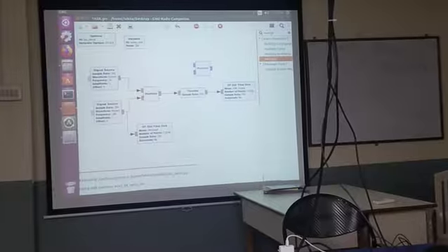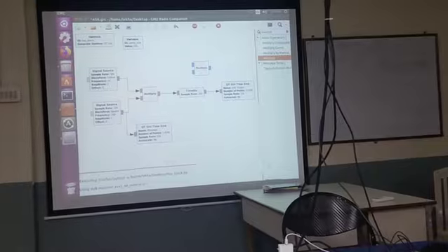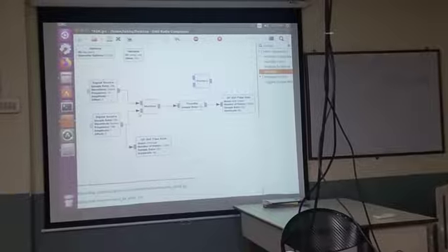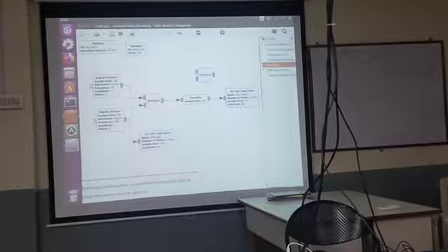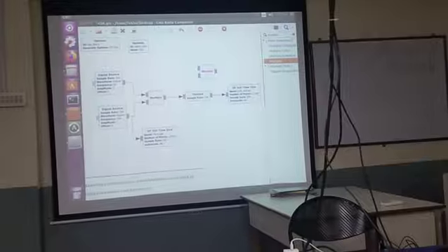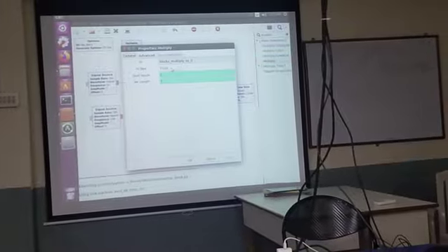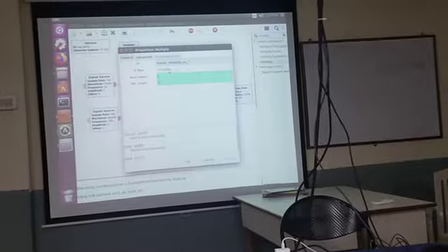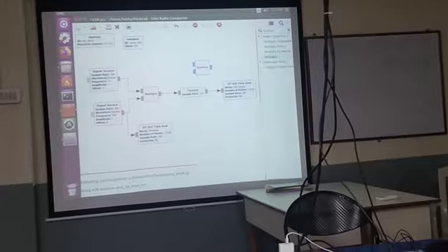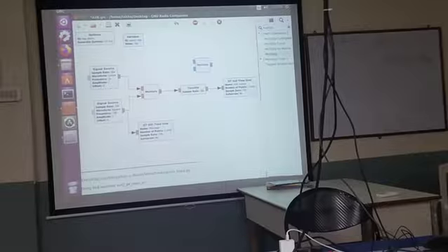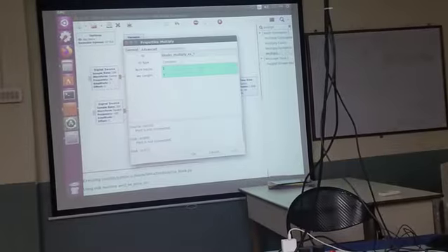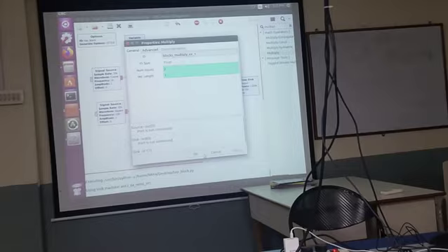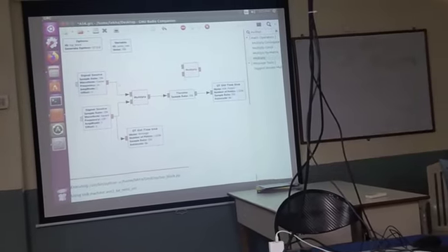One more thing we have to note is what kind of data type we are going to use here. You can see the difference in color for the data types. Here it is showing blue, and this is orange. The orange color refers to the floating point data type, whereas blue is a complex type. All my data types should be matched here, so we have set all the data types to orange. You have the option of changing from complex to floating point, integer, short, and so on. So this is how the multiply block is chosen.